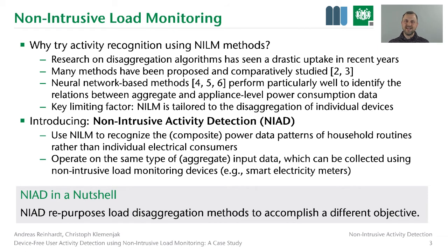And that's exactly why we are proposing NIAD, Non-Intrusive Activity Detection, based on the concepts of NILM, but translated away from recognizing individual appliances and attributing them energy consumption and corresponding cost, towards using NILM to recognize activities and thus infer what the users are currently doing.